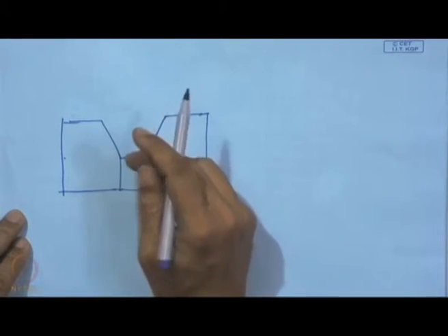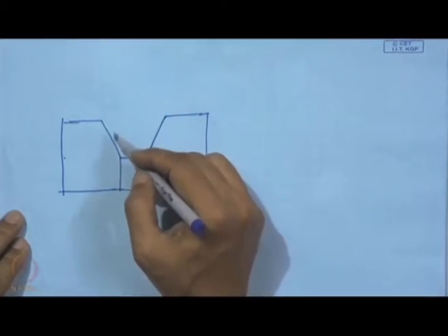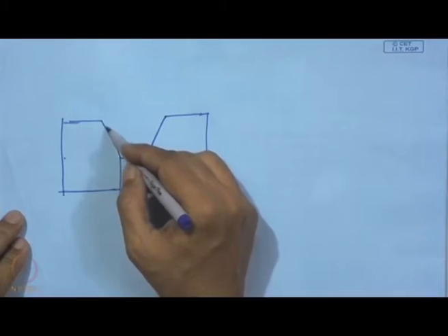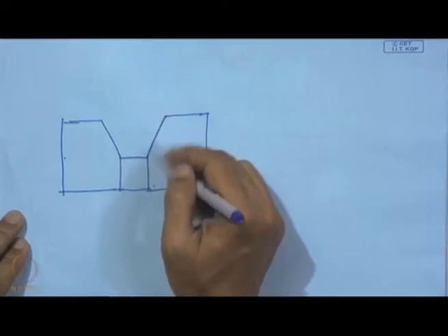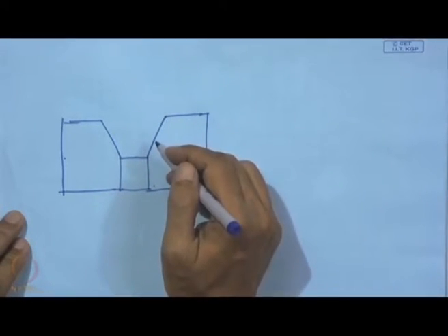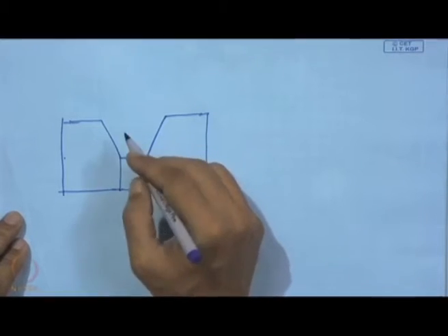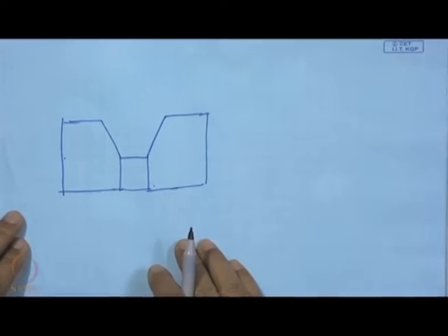Now, here during locking and opening there will be stress reversal. So, these surfaces will have a change of stress, that means they will be submitted to some alternating stress, and that means it is going to be a fatigue.